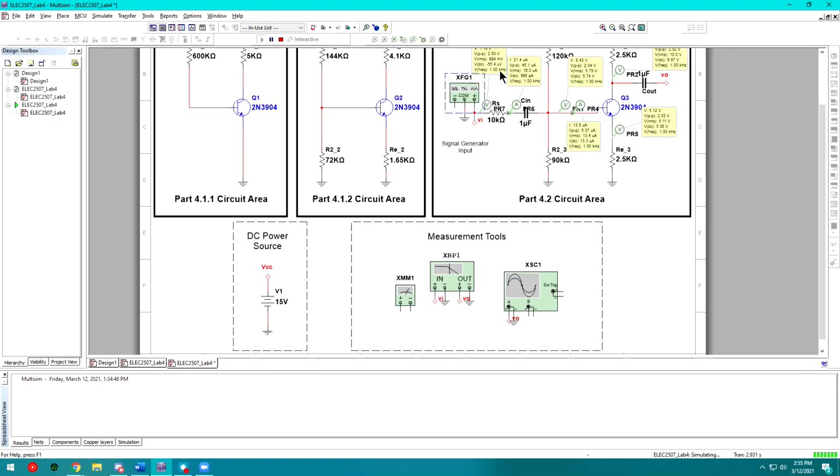So, that being said, we can do 2.5 volts peak to peak divided by 45.1 microamps peak to peak, and we can come up with a small signal input resistance for this particular amplifier. From this calculation, I found that my small signal input resistance is approximately 55.25 kiloohms. So that's not a great amplifier. It's alright. It definitely could use some modifications to make it a little better.